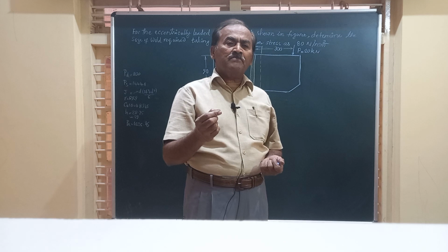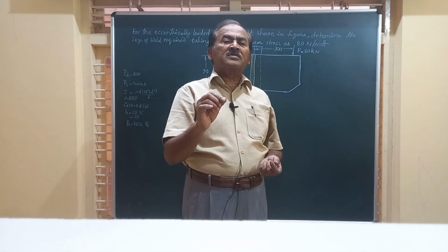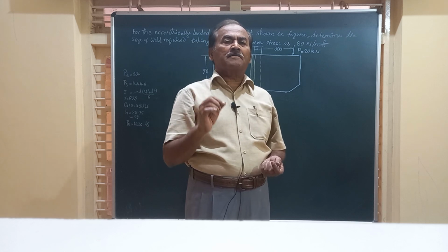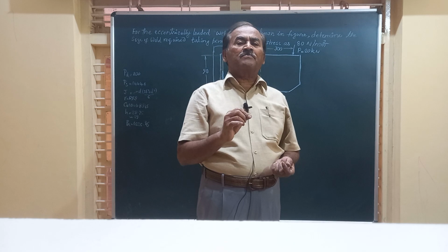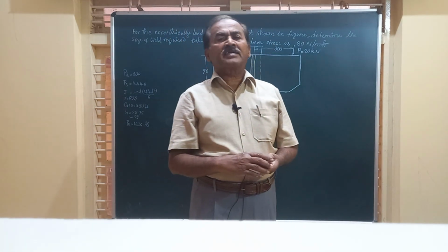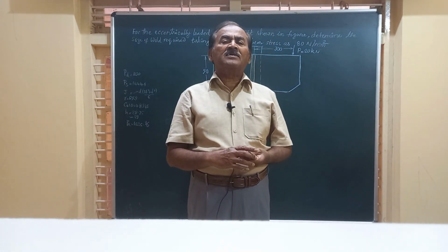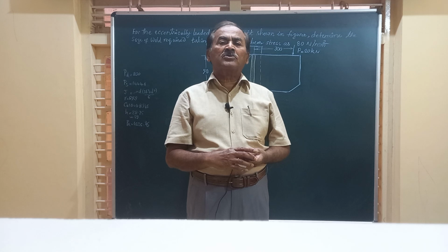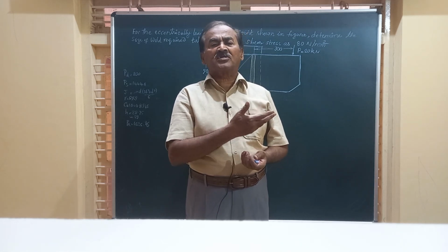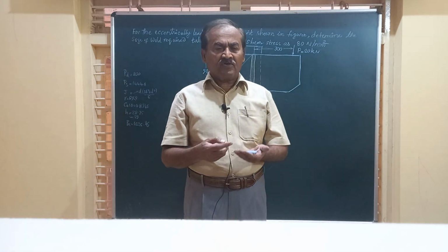In the third step, we find the secondary load and its orientation with respect to the point where it is acting. In the fourth step, we find the resultant of the direct and shear load. And finally, we equate the resultant load to the shear strength of the weldment and find out the size of the weld.